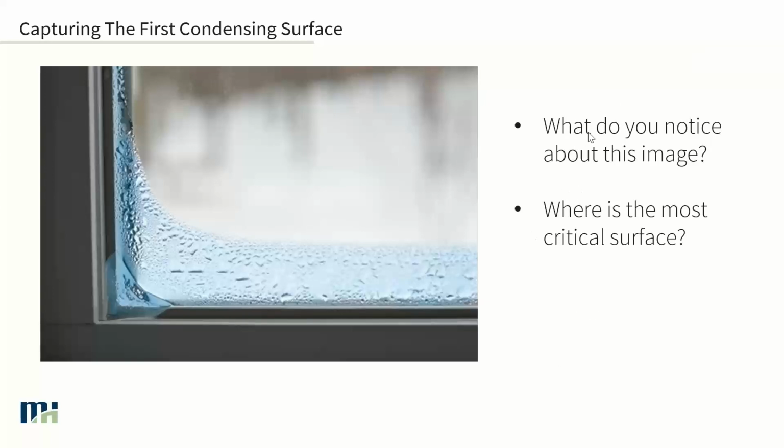So yeah, it's not just condensation on the interior, but really that corner. It looks like it's got a little bit of frost occurring there. Over here, it's still condensing, a little bit less on this edge. But if we were just to do a 2D analysis through here, we would just get surface temperatures that are above zero. If we look at the corner, we have temperatures that are below zero, and it's causing this to frost over. So that's something that's missing when we're only looking at it from a 2D perspective. It's not able to capture that.